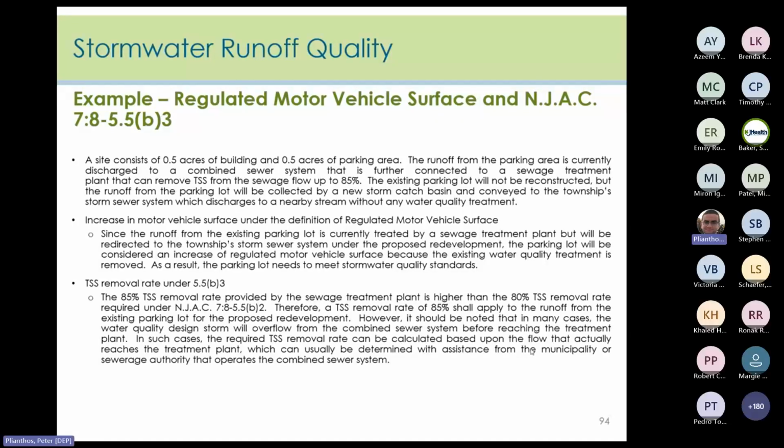The 85% TSS removal rate provided by the sewage treatment plant is higher than the 80% TSS removal rate required under N.J.A.C. 7:8-5.5(b)2. Therefore, a TSS removal rate of 85% shall apply to the runoff from the existing parking lot for the proposed redevelopment.